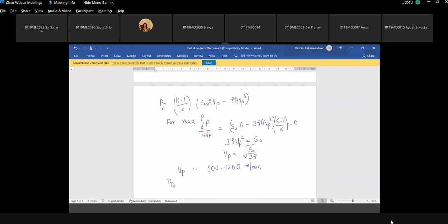So when we are designing a belt, we have to select the material of the belt. We have a choice of material given in the data book. We have to assume the section of the belt, whether it is rectangular or square. We have to assume or calculate the length of the belt, and we have to see what kind of joint. A flat belt is not seamless, so somewhere there would be a joint. The type of joint would decide the efficiency. That is again given in the data book.